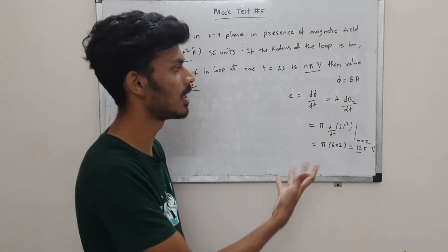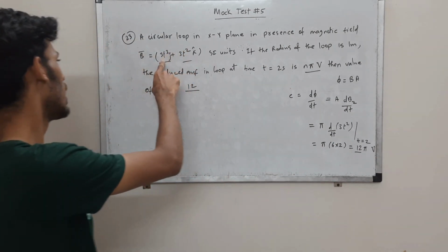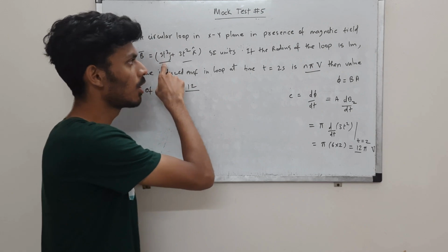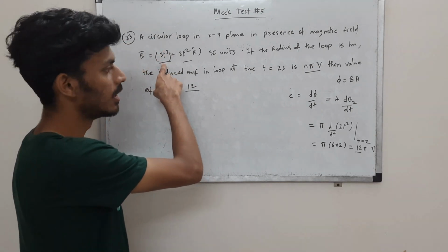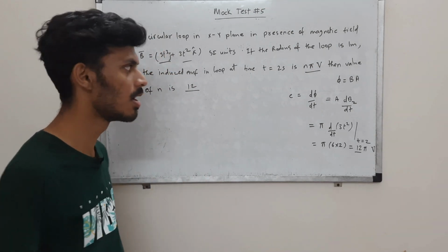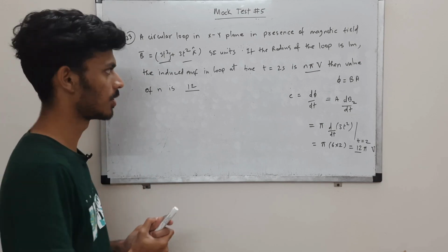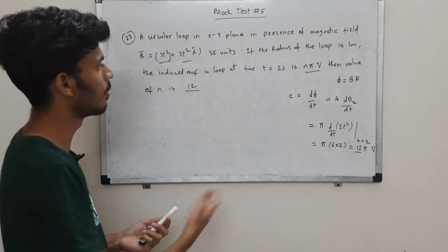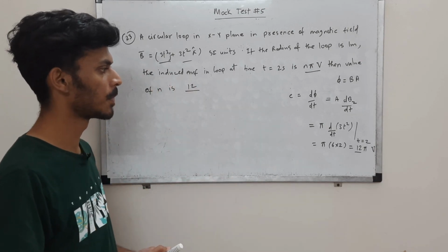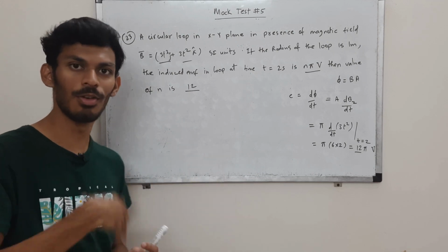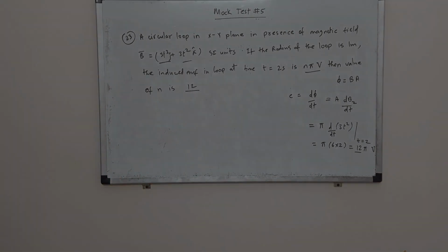Pretty straightforward. You have to keep in mind that you should not take the value in the y direction, because that is not contributing to flux, and that is not contributing to induced EMF. So that was the only point to focus on. Over to the next question.